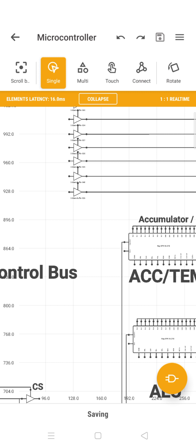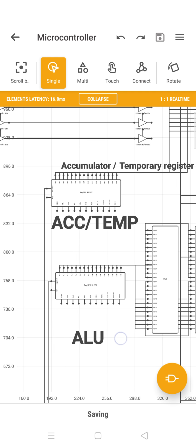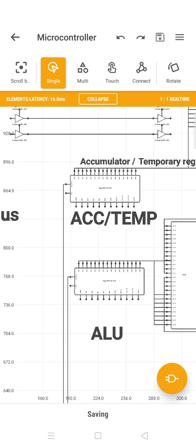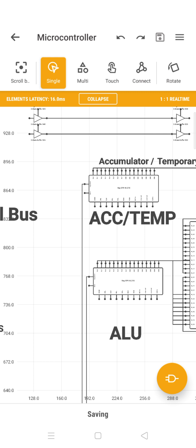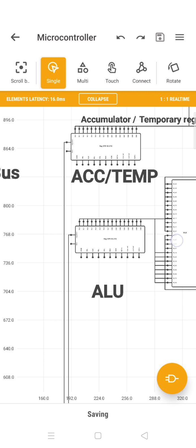Hello everybody. Last time we saw how a microprocessor works and what the different kinds of bus architecture are. Today we are going to see specifically about the 8085 chip, a microprocessor which was released a long time ago. It is an 8-bit data, 16-bit address processor. It has 8 address bits and 8 data bits, which are multiplexed, and totally around 16 bits for usage. That is what we want to see right now.